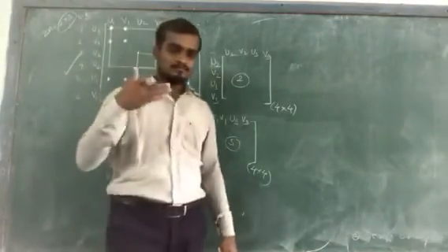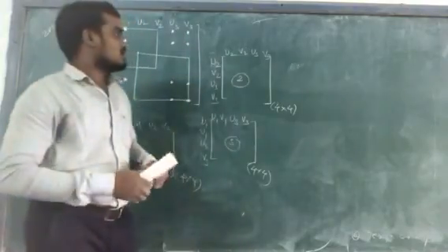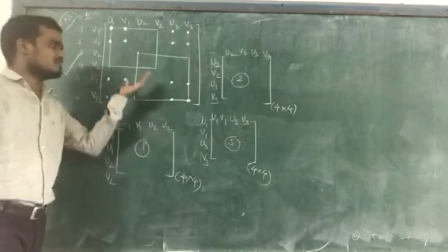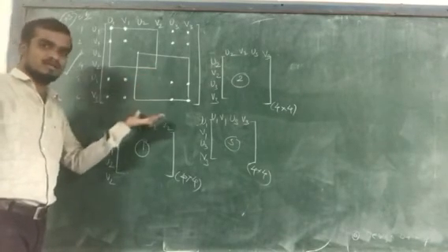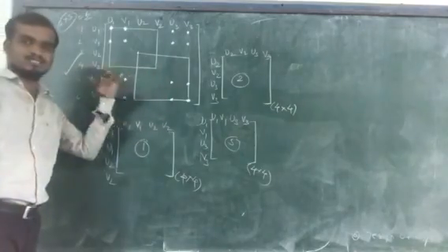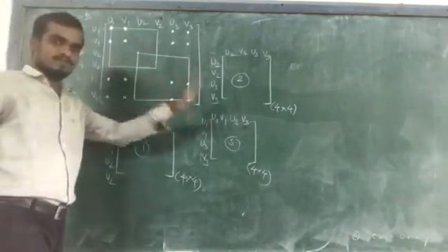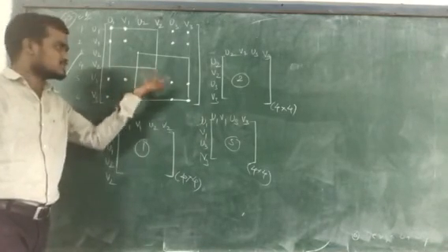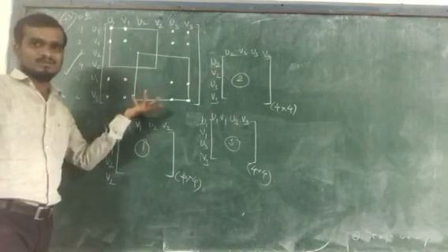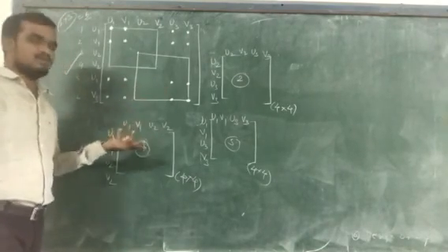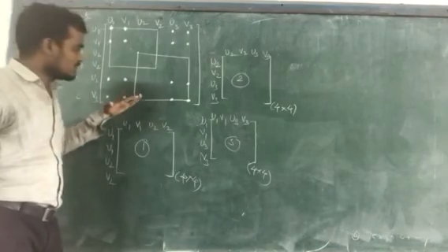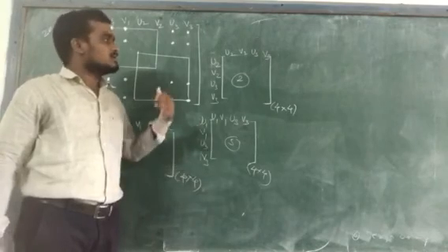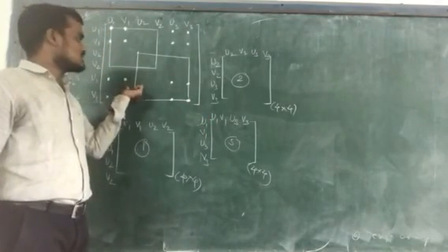And then we can solve. The next procedure is the same, means apply the boundary conditions. After applying the boundary conditions, you will get the eliminated equations. By using these eliminated equations, you will get the displacement values. By using the displacements, you can get reactions, then stress values in each element. The stress formula is the same, we will see this during our example. So up to here, we will get our global stiffness matrix. In the next lecture, we will solve examples related to the truss element.